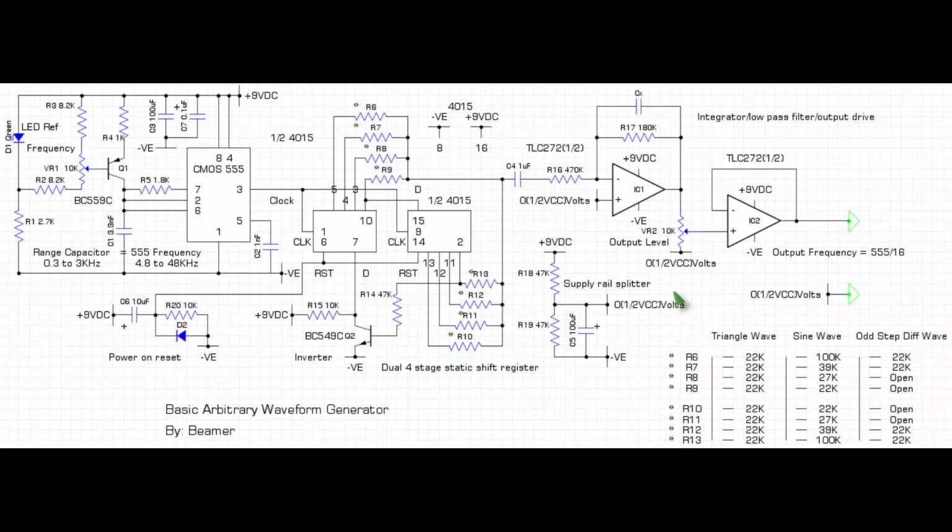Other than that, quite possibly the 30 hertz to 30 kilohertz is a bit limiting, and I probably would like to explore a higher frequency option, maybe 10 kilohertz to 100 kilohertz, but bearing in mind that the driving oscillator would always need to be 16 times that.